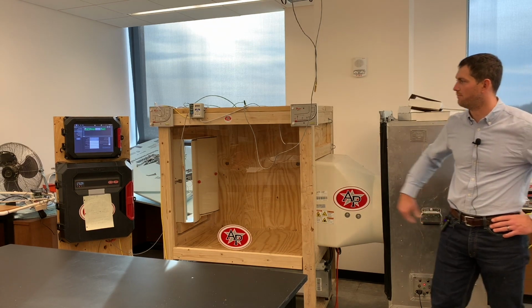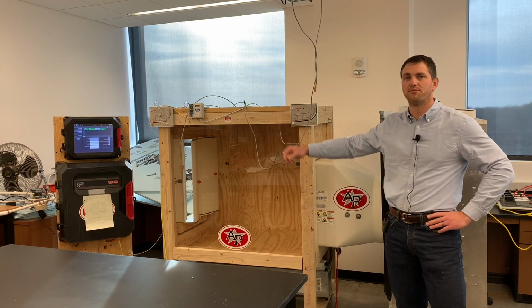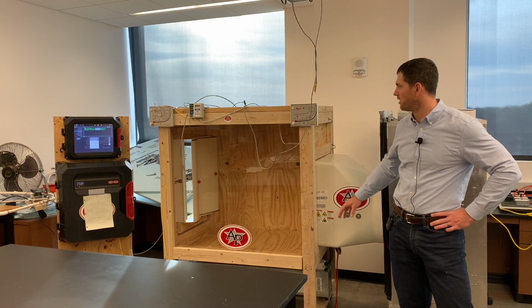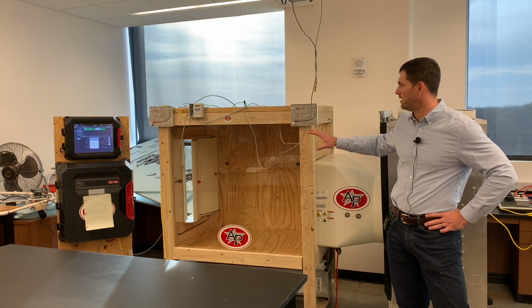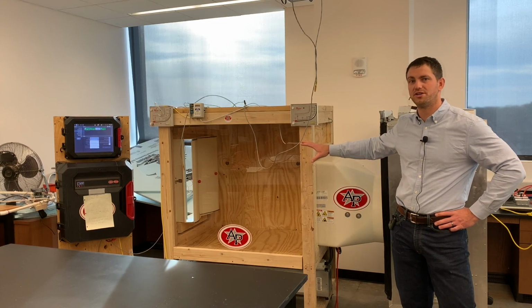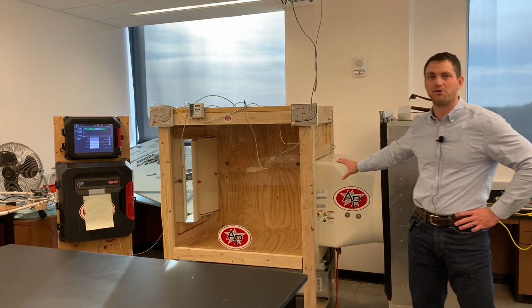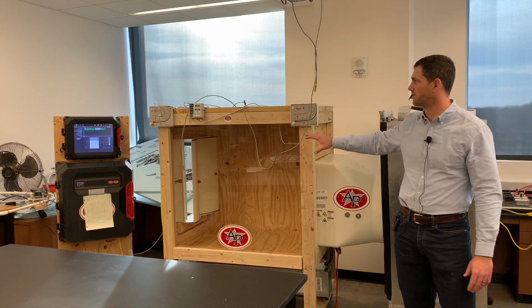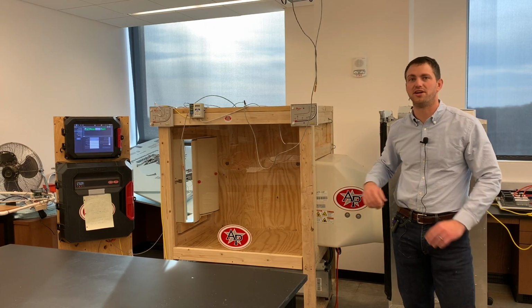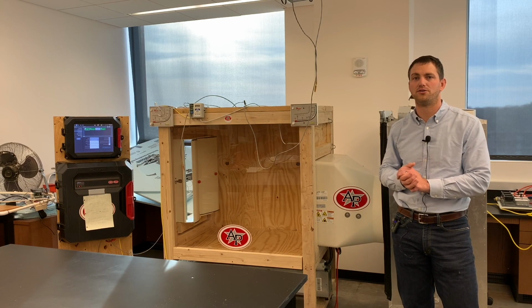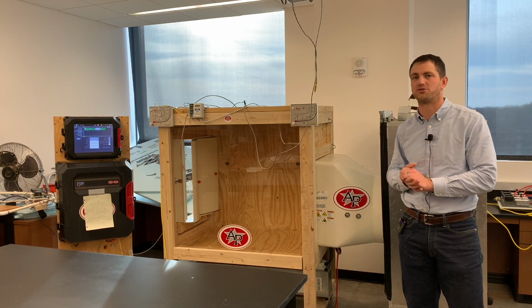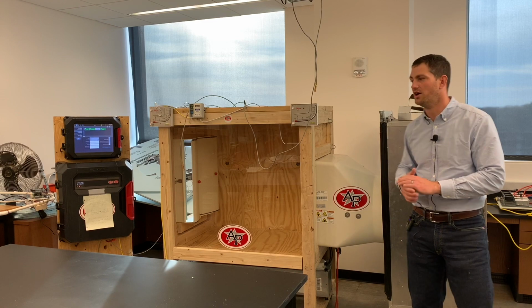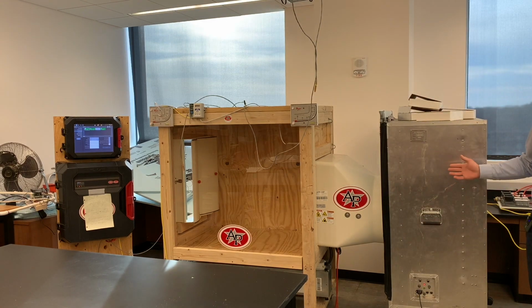Here we have a modern control system for controlling the ventilation. We also have a ceiling inlet for fresh air distribution and a typical ventilation fan for a swine facility. And here we can demonstrate pressure curves so students can relate airflow to static pressure, which is a critical driver of ventilation. We also have a fans unit for measuring airflow.